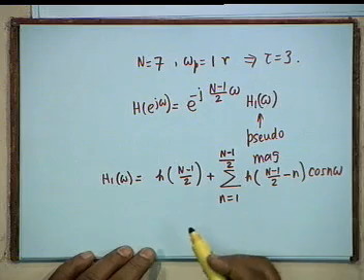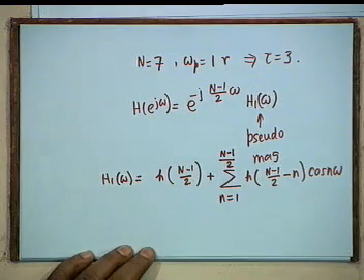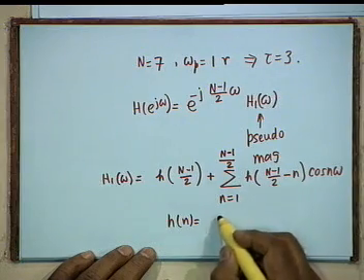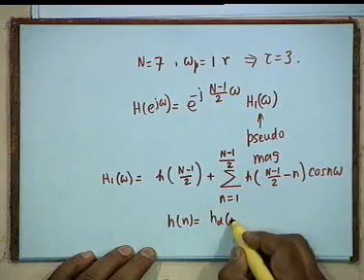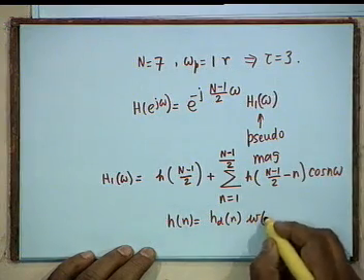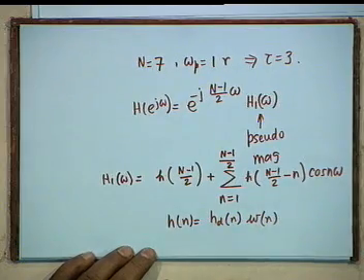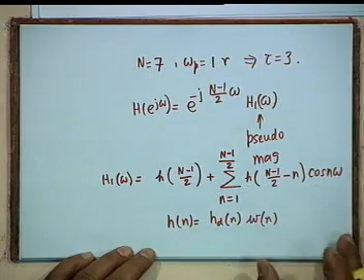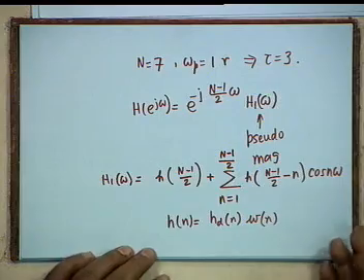Now, so these h's have now to be obtained. h[n] is to be obtained from h_d[n] and the chosen window function w[n]. Okay. So once you obtain this, you substitute here and then you get the frequency response.